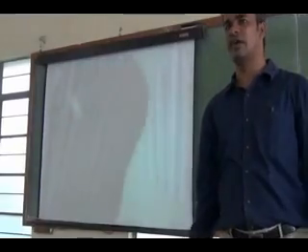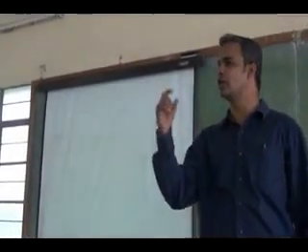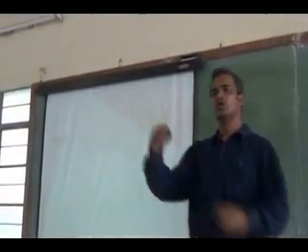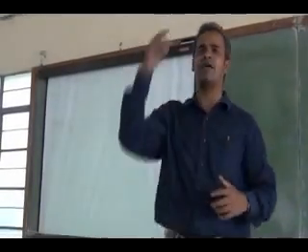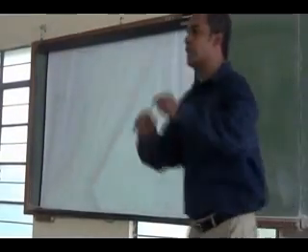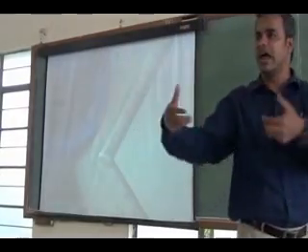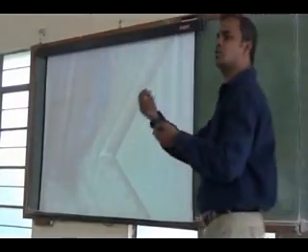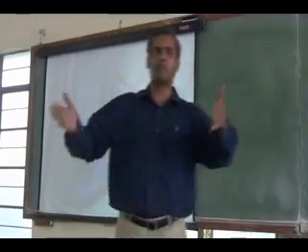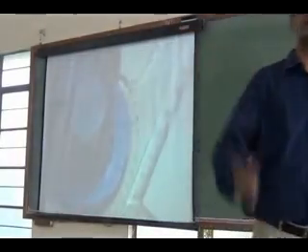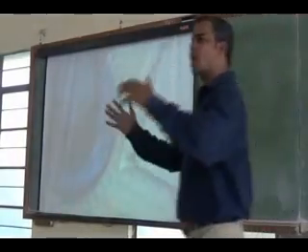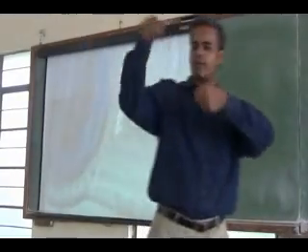Look at your drafter. Each grading is 2 degree, so in between 0 to 2 degree I will definitely have an error. Why? Because the drawing sheet may not be cut properly, so the layout line you have drawn can have an error. The drafter as you have fixed it may have a small bit of error, and the paper as you have fixed it may have a small bit of error. All together it gets accumulated and comes into your 0 error.